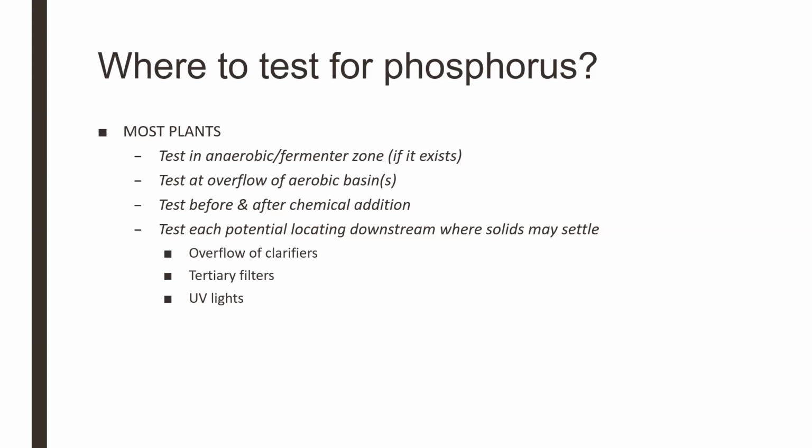There might be some sort of a basin or a box there. There might be a splitter box where solids could potentially settle out. There also may be areas before tertiary filters or UV lights, or even if you still have chlorine disinfection, that would be another potential location.